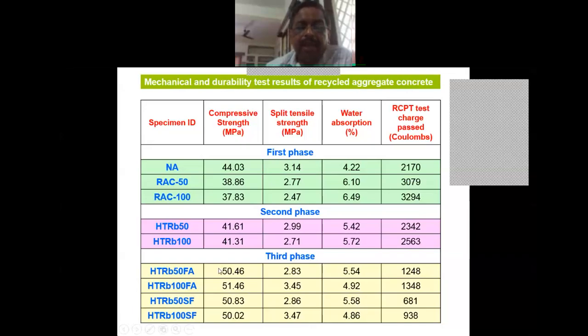And here, because we are adding in addition to cement, as we know, whenever extra mineral admixture is added, there is an improvement in strength. So even if you had added this 5% and 10% mineral admixture in the natural aggregate mix also, it definitely might have gone to a higher value. So here this improvement is not because of the aggregate replacement only, but because the cement replacement material has also improved it. So both ways we can have it.